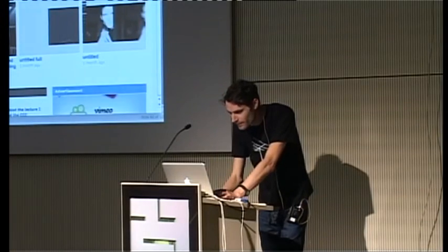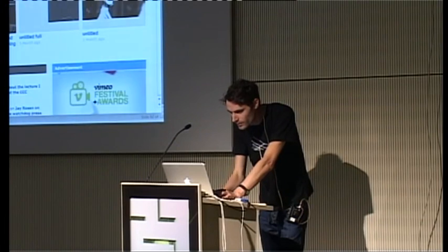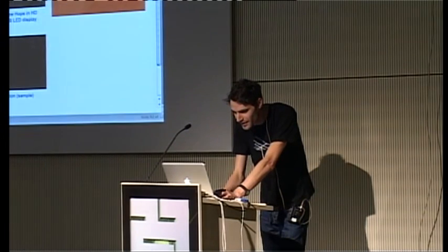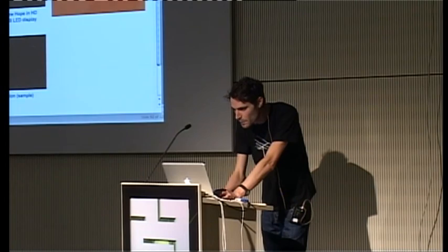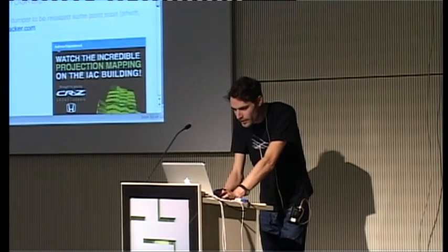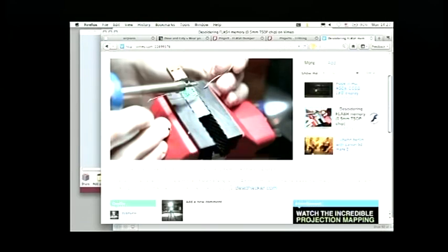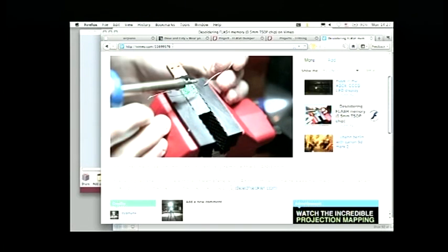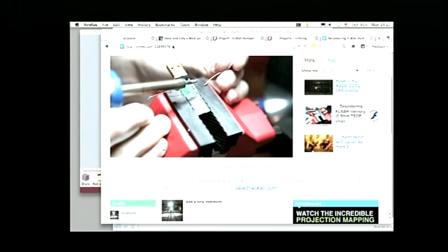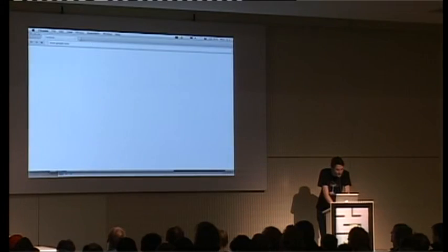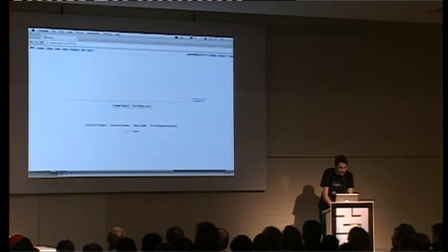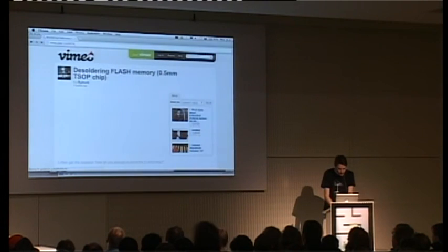Sorry. Show you real quick. Okay. So removing the chip is a lot easier than it seems. All you need is a soldering iron and solder and some solder wick, perhaps, to remove the solder and clean it.